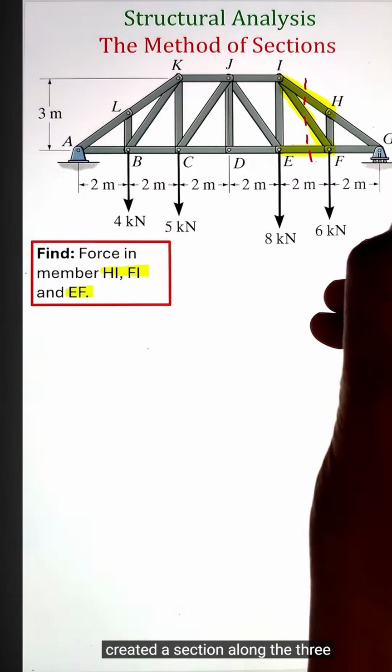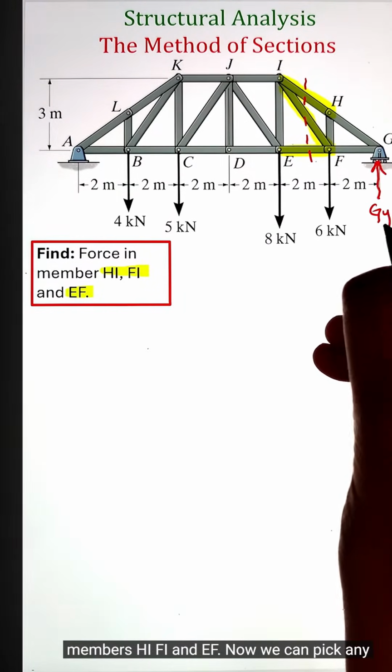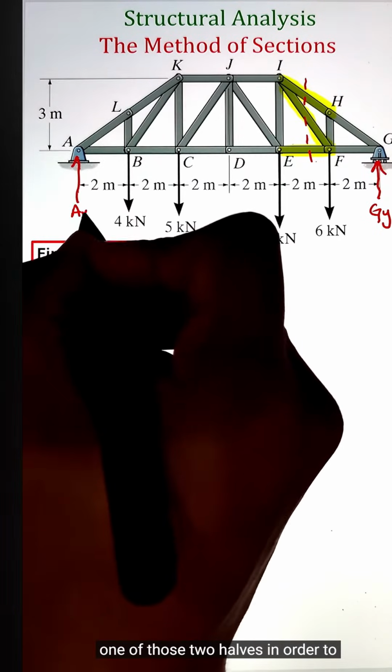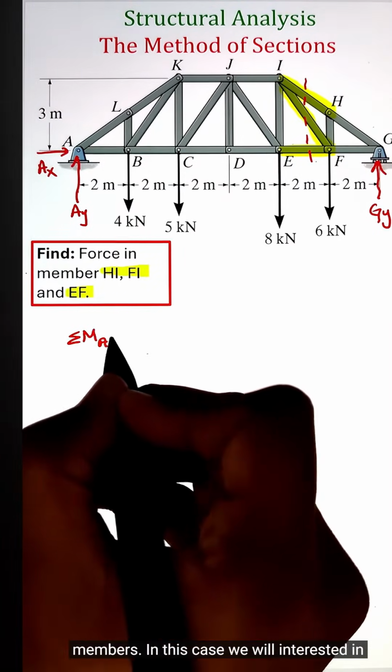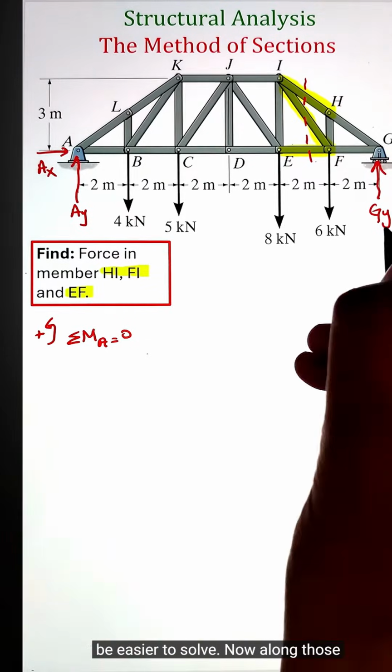Here we have created a section along the 3 members HI, FI, and EF. Now we can pick any one of those 2 halves in order to figure out the reactions along those members. In this case, we will be interested in picking the smaller half, since it will be easier to solve.